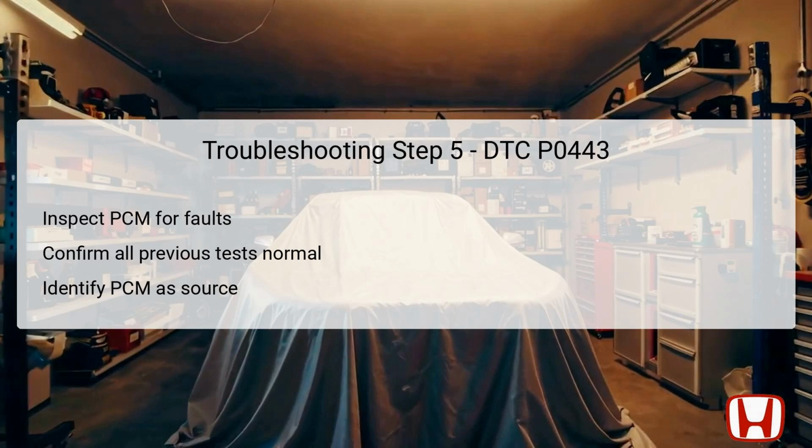This module is the brain of the engine management system and directly influences the performance and diagnostics of various components, including the Evap system. If it is determined that the PCM has become faulty, it may require recalibration or replacement to restore normal operations. This step is critical as it involves the evaluation of the component that ultimately manages how the entire system operates, reinforcing the importance of thorough diagnostic processes throughout the troubleshooting.